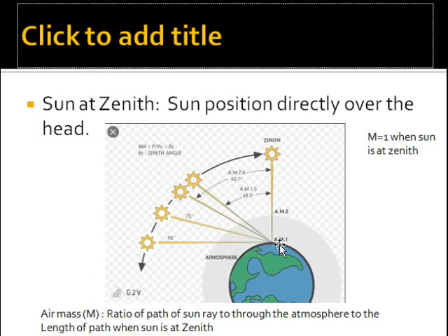So that means if air mass is 1, you will get a transmission factor of 0.633. Like that, at some distance, when the inclination is very high, at that point air mass is 5, and you will get some light energy, but the transmission factor will be only 27%, that is 0.276. These values you can get from the textbook.